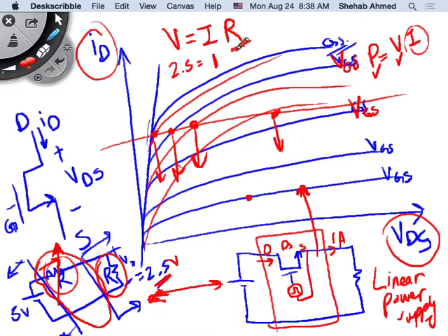So there's a lot of power loss associated with this circuit. It does the job, but there's a power loss associated with it. How about this type of circuit? They short out really easily. Same thing, right? You're still dropping a voltage across a device. If you drop a voltage across the device and there's current flowing through it, what do I have burning through? Power. It's voltage across and current flowing through: P equals V times I. So I'm burning power through the device. I'm burning the same amount of power through this MOSFET as I am through this resistor,